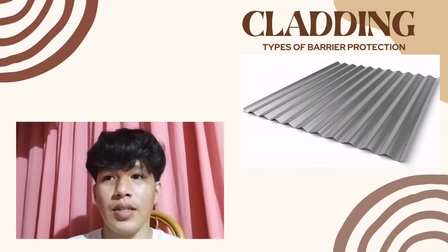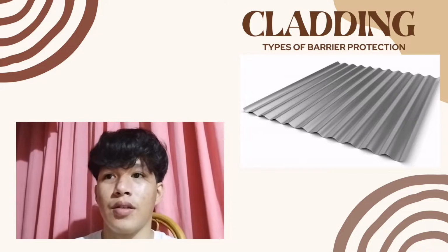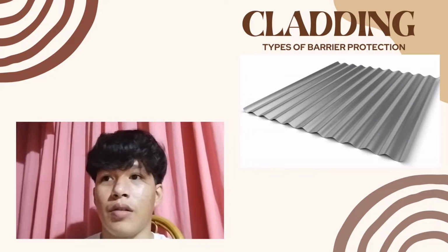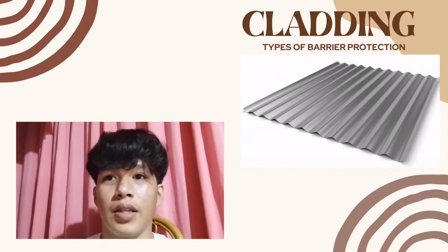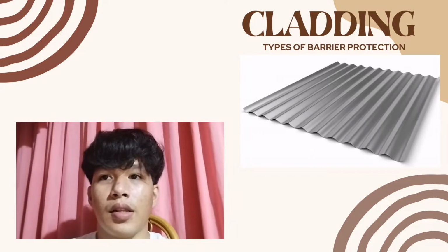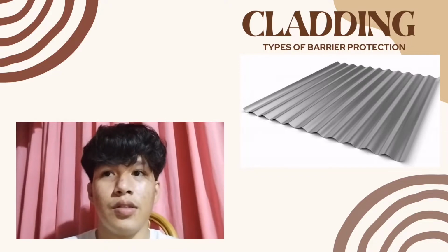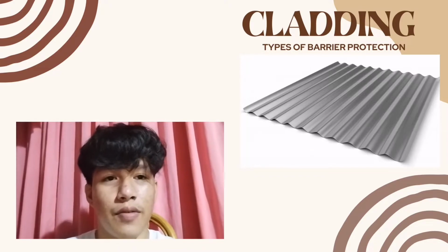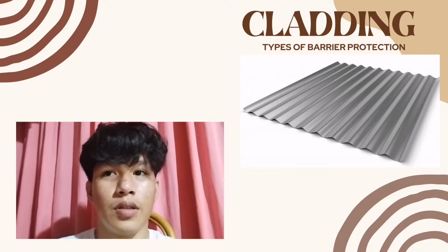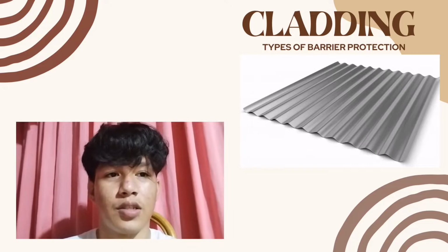Cladding. Cladding is a process of layering materials to protect a structure from weather elements and to provide exterior finishing. Metal cladding is a type of protective coating where the protective material, such as metal powder or foil, is bonded to a substrate by applying heat or pressure. The study of metal cladding is significant because this method of corrosion protection is generally very reliable and cost-effective. In addition, the process parameters can be optimized for different metals and composites in various critical applications.